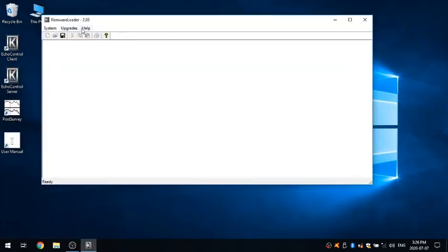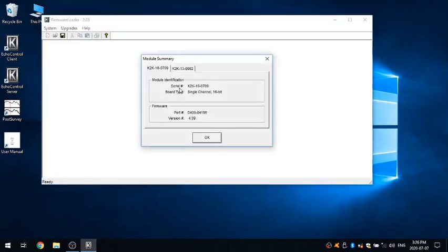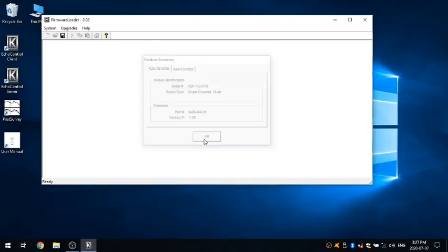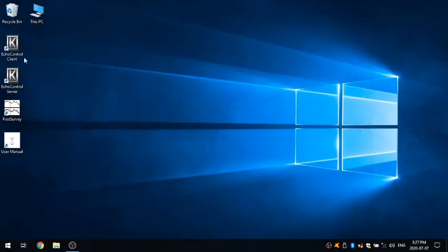Now, if we go back to the menu under Help, Sounder Info, if you remember previously, the channel modules both were at version 4.07. So now we can see that both of our modules have been upgraded to the new version 4.09. As I said, this is a very good thing to check afterwards, because you want to make sure that they have both programmed. You don't want to have one module at one vintage and the second one at a different vintage. So in this case, both of them are upgraded, we're at our new version, and we're ready to go with our upgraded version of SounderSuite.